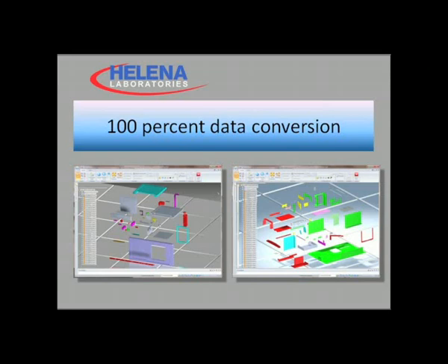Okay, this shows that wireframe model imported into Solid Edge. On the left is the machined components of the Spiffy 3K. On the right-hand side is the sheet metal parts imported into Solid Edge. And, with live rules, with Synchronous Technology, we have 100% usable data. In just a few clicks, with the sheet metal side, we create a sheet metal model, and in just a few seconds, we can flatten the part that was drawn in wireframe 10 years ago.